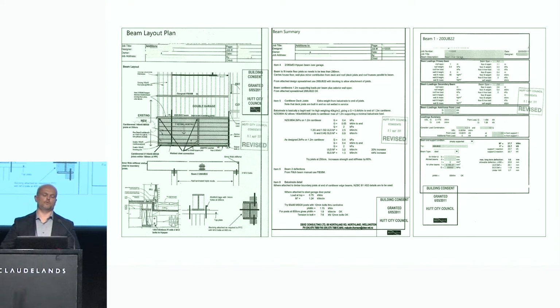From some of the big projects that we've seen lately, structures are not standing up under gravity, and so I really recommend you put your gravity system at the front, because your lateral restraints and all of that sort of thing, as Rob Jury said a little while ago, really all of the lateral system is there to keep your gravity system intact, and it's stuck with me. So the gravity system stops things falling on our heads.